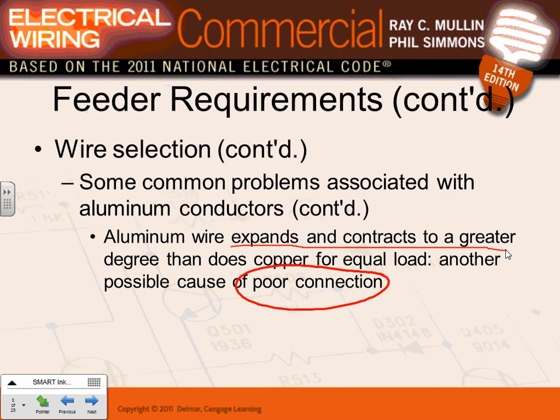What happens if you have a loose lug? Arc flash. Anybody know what an arc flash is? A fire inside your building, inside your panel, right? To avoid this, what do you do? Put them on a preventative maintenance program. Maintain them. Measure the temperature of the lugs annually. Retorque all your panels. Done. You can avoid a poor connection by torquing them, because over time they loosen up. Go there and torque them.